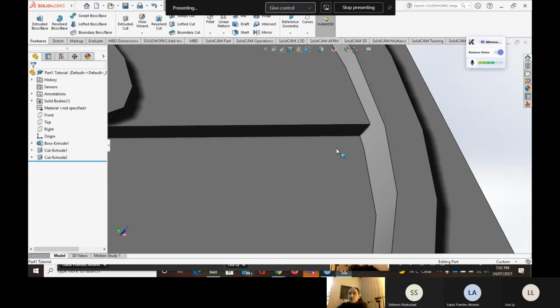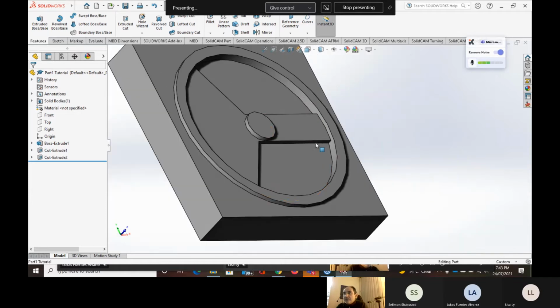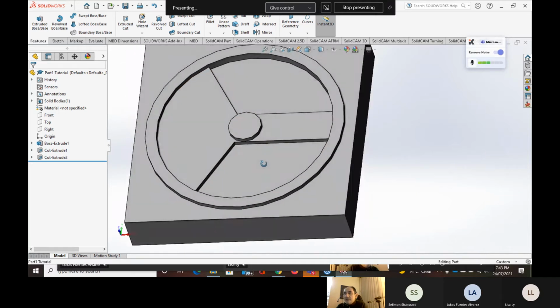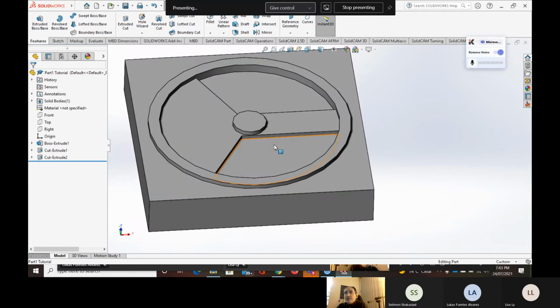Maybe you can do that by approaching operation, where the device is going to go forward and backward and cut the edge using a single tip cutting tool. But for this one, it's impossible to be done by the milling operation. So the milling is always going to be a fillet shape, and the fillet is going to be generated by the cutting tool movement around the corner.